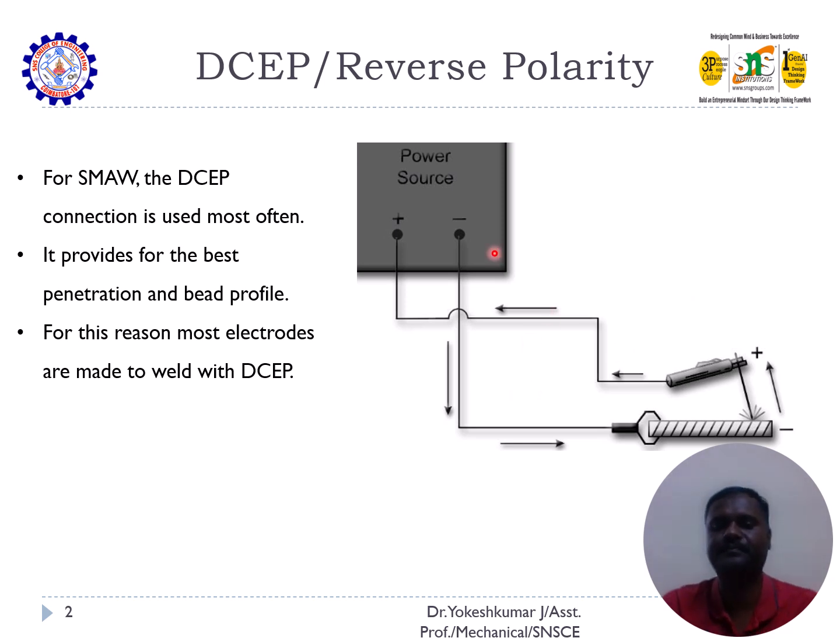In this illustration, the arc is struck between the positive and negative terminals. We have a potential difference between the two points, and a short circuit is made between positive and negative. This is a controlled short circuit which generates an arc between the electrode and the workpiece. This arc generates an enormous amount of heat that is used to melt the parent metal. Sometimes filler metal may be added, and filler metal may not be added in the case of very thin welding. If the workpiece is very thick, we need to additionally add filler metal.